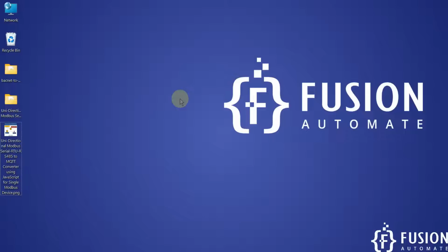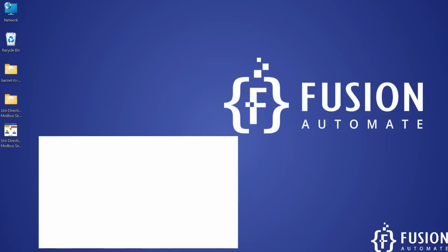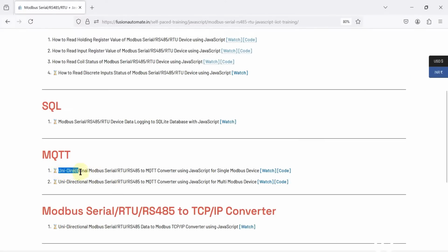Hi everyone and welcome. In this video we will see a unidirectional Modbus serial RTU RS485 to MQTT converter or publisher using JavaScript for a single Modbus serial device. So your JavaScript will act as a Modbus serial master which will connect to your Modbus serial device, and then it will publish your Modbus serial device data to the MQTT broker.